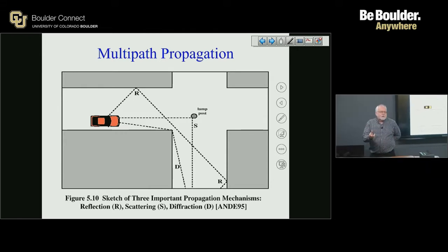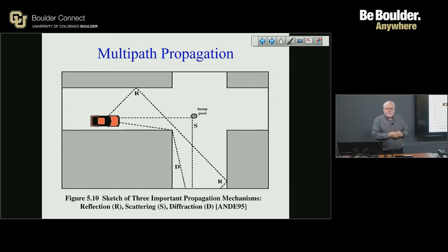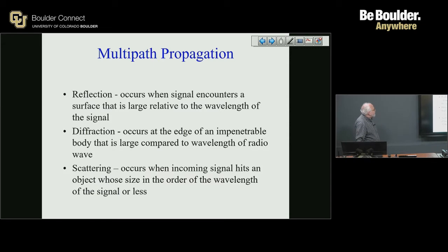And you're actually usually indoors, you're getting so much reflection. It's amazing to see how much of the energy is actually being reflected into your laptop, especially in a non-line of sight scenario. So if the access point's outside, what you're getting, especially with OFDM, is all the reverberations. It's collecting that and trying to accumulate all that energy. It's one of the advantages of OFDM that we'll talk about more. So refraction, diffraction, and scattering. Scattering happens a lot in millimeter wave.